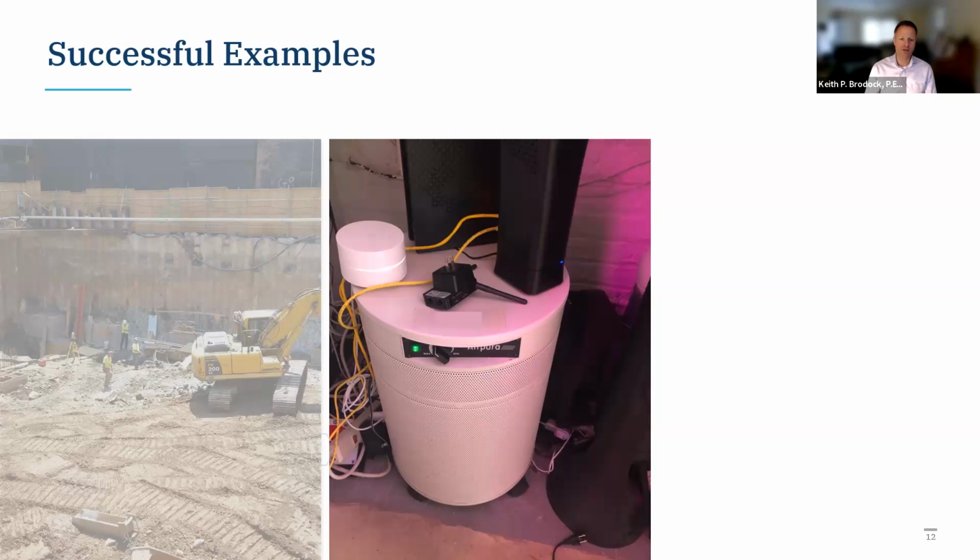And it also allowed us to then go into folks' homes and be able to install these canisters. This is an air filtration system that has granular activated carbon in it, and it takes out the volatile chemicals from the air. We put these in, and we also install the subslab depressurization system, both as interim remedies, right? It wasn't going to completely clean up the site, but it was going to help limit the vapor intrusion pathway into the building while we design this full-scale remedy that's designed, and we are just waiting on approval.